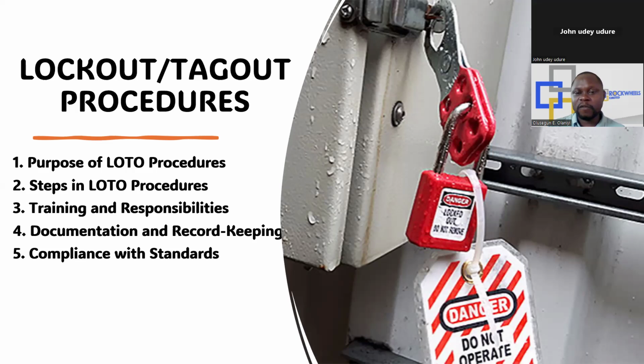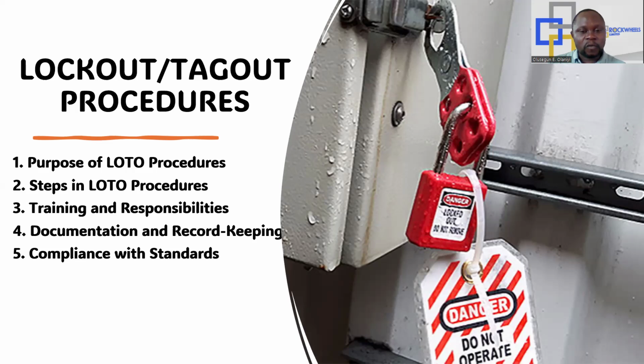Application of log out, tag out devices: also apply log out, tag out devices to energy isolation points to prevent re-energization. This will help you to avoid re-energizing so that somebody will not come and energize the equipment. And if you think that you are not going to tag it, you just lock it, somebody will just come and maybe if the key is available, the person will unlock it, untag it, and then continue with the work. So you use tags and you lock it.